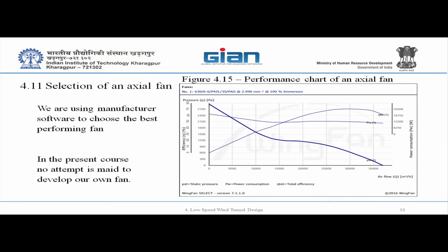The total pressure is the jet power, and actually jet power is dynamic pressure, and then the pressure loss in the circuit is again pressure. You sum up and you get some pressure that the fan will have to work against. So that's the working point it will have.